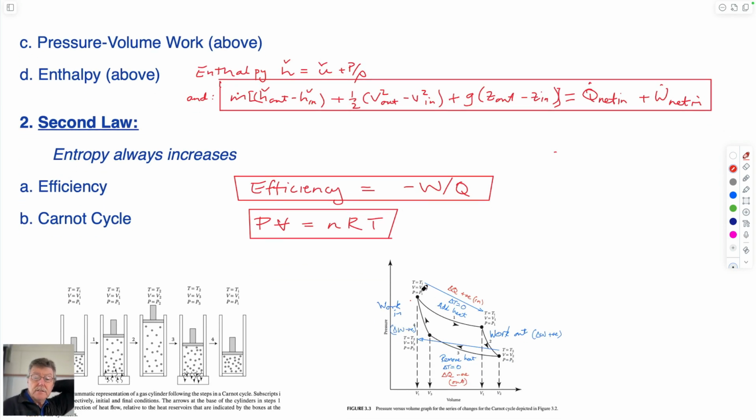we're not going to spend all the semester talking about heat engines as a system, but it's a useful vehicle for us to discuss energy and work in these systems. Mainly we'll be dealing with the subsurface behavior. So we can define enthalpy as internal energy plus pressure divided by density, which is the same as internal energy plus pressure times specific volume. Lowercase v was equal to 1 over rho. This would be of the fluid in this particular case.